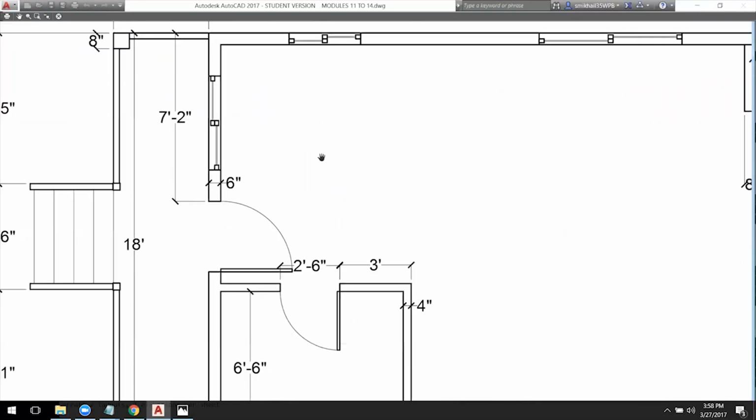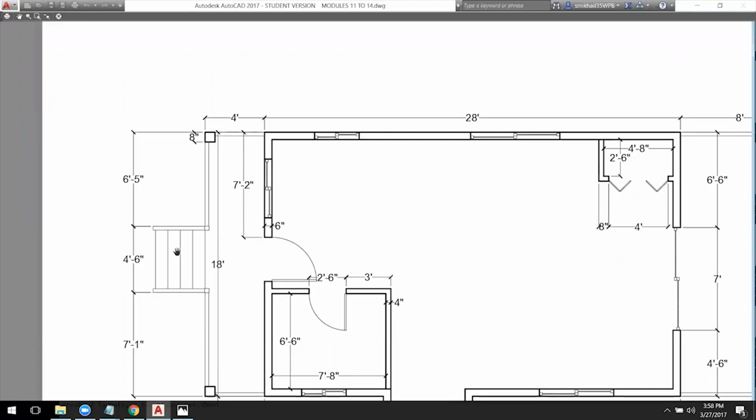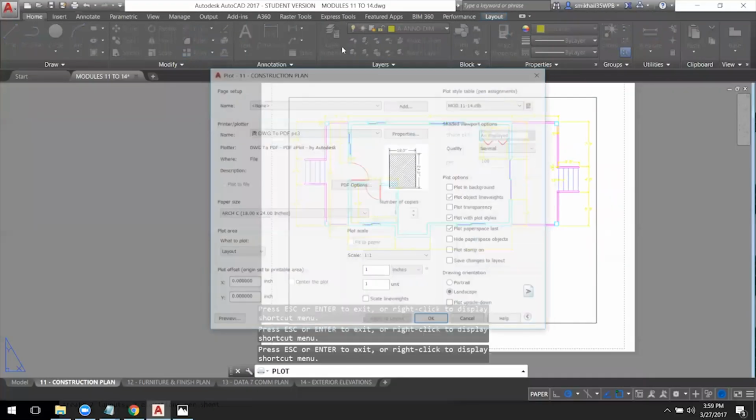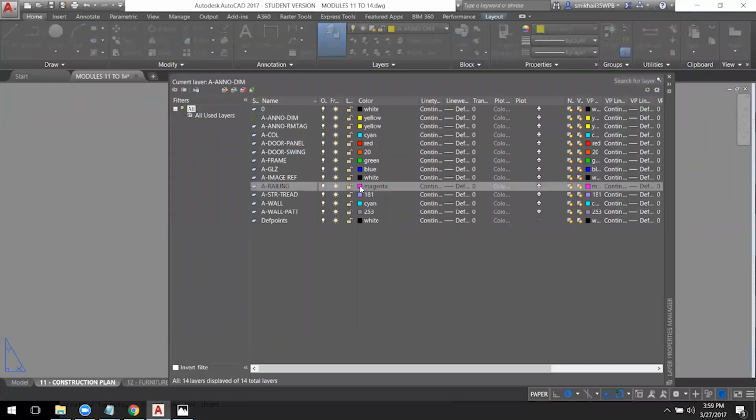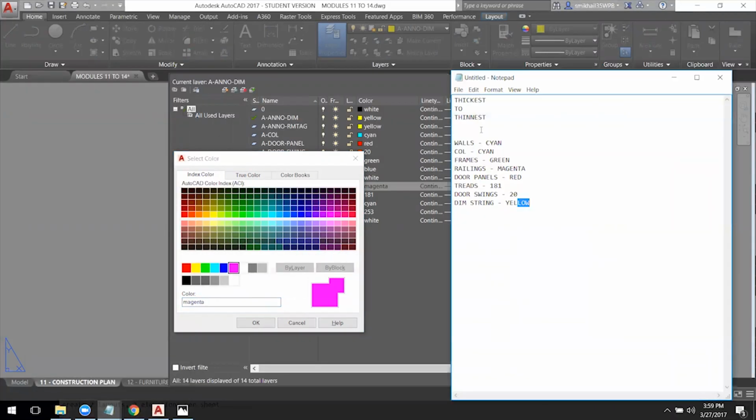Play around with it, and once you submit your drawing, I will take a look at it, and I will give you advice on what you should make thicker or thinner. You will need to probably keep your color selection somewhat organized. You don't want to go all over the place when you are selecting your layer colors in here. You want to try to stay in order. Perhaps you can go with color 1, 2, 3, 4, 5, 6, all the way to 10 or 20 or however many layers you will need, rather than just jumping all over the place, because you will require to do something like what I did in here, basically a legend that tells me what color is what. So when I'm in the CTB settings, I need to know what color I'm referencing for each type.